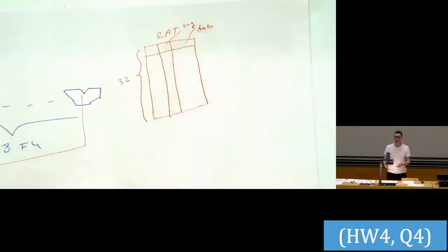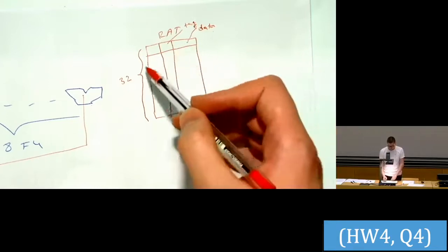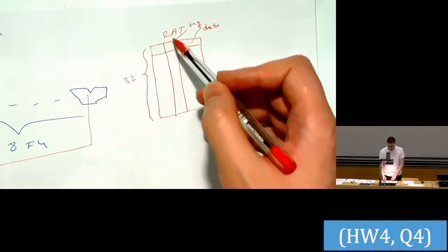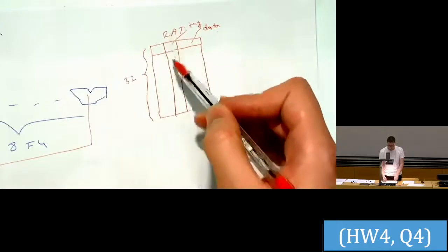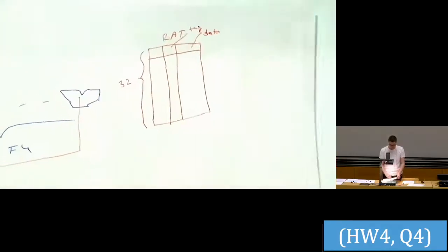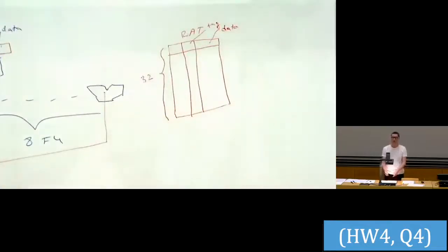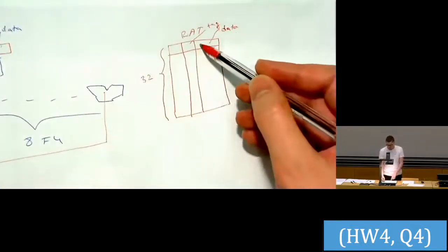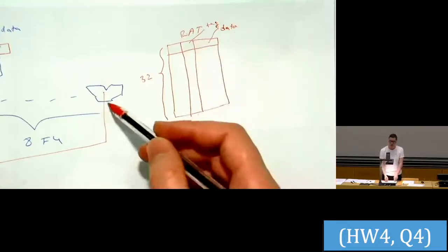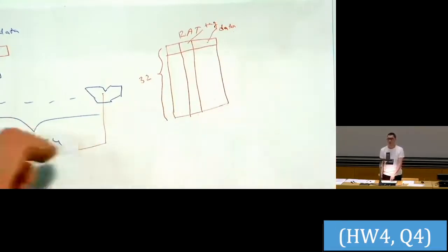And it will also have some valid bits. So basically, we also have some comparators here, one comparator for each tag. And then it will again be multiplied by the number of functional units, because in a single cycle, we will need to compare those tags against each of the results coming out from the functional units.